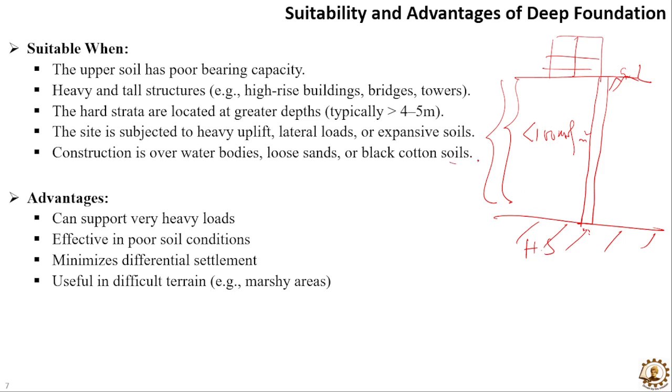Similarly, if the hard stratum is present at a depth greater than 4 to 5 meters, we will also use deep foundation. And if the site is subjected to heavy uplift, lateral loads, or expansive soils, we can also use deep foundation. Uplift means, for example in bridges, the cylindrical member has a tendency to go upward, or there is some lateral load, that means earthquake or wave action. In such situations we prefer deep foundation over shallow foundation.